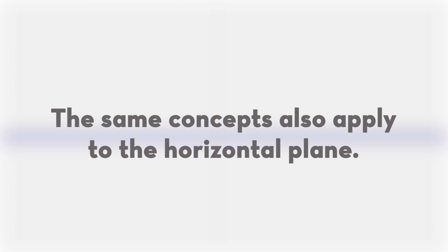In graphical view, the horizontal length of each square represents 1 inch, while the vertical length of each square represents 5/1000ths of an inch. While we'll only be working in the vertical plane, the same concepts also apply to the horizontal plane. Before we start, let's measure and indicate in our graph view the positions of the front and back feet of the stationary machine, the center of the coupling, and the front and back feet of the movable machine.